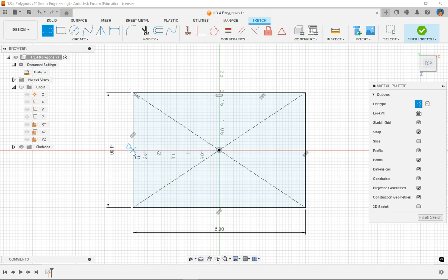I'm going to go over to my left edge. I'm going to make sure I'm at my midpoint. I should be directly on that red line. I'm going to drag across to the other side. Again, I'm waiting for the midpoint, which should again be directly on that red line. I'm going to click. I'm going to do the same thing for the green line. So I should be lined up so that my midpoint constraint shows up right there.